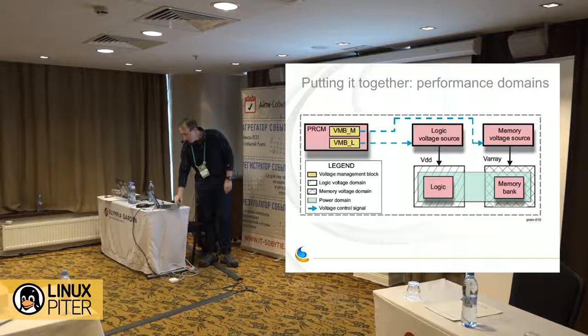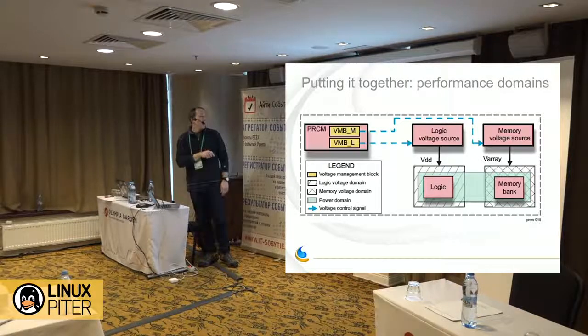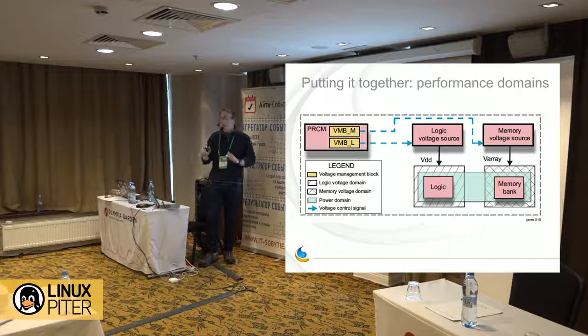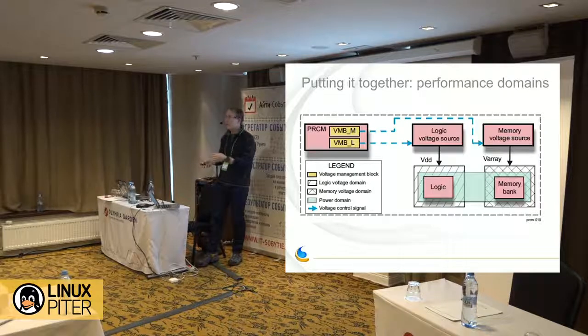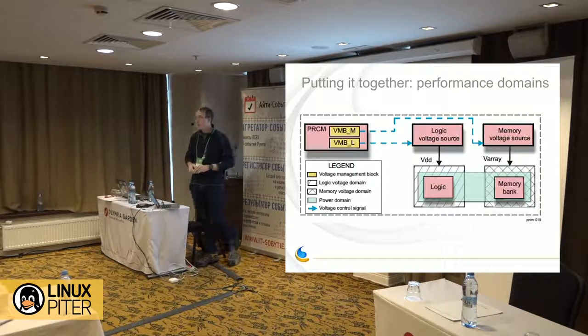All right, we're almost done with our electronics overview. So performance domains are analogous to the idle domains we just discussed, right? It's electrically isolated transistors. They're typically going to be fed by a dedicated SMPS or regulator. And what they do is you can scale voltage. Remember before we talked about scaling voltage on a slider, high voltage, low voltage, as a function of performance. And so that's what these can do.